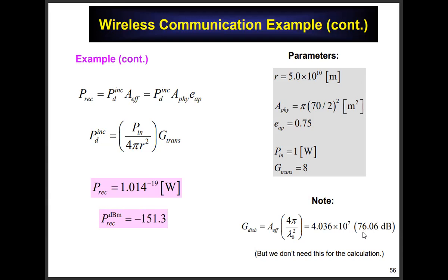Now, it would be hopeless to try to pick up a signal from a CubeSat at Mars down here on Earth with a resonant wire antenna. That would be absolutely hopeless. In that case, it wouldn't be minus 151 dBm. It might be something like minus 1,000 dBm. I don't know, whatever. It'd be absolutely hopeless. At least this has some hope. Again, the bit rate might be a few bits per second, but they can still do it. Okay, all right, anything else?